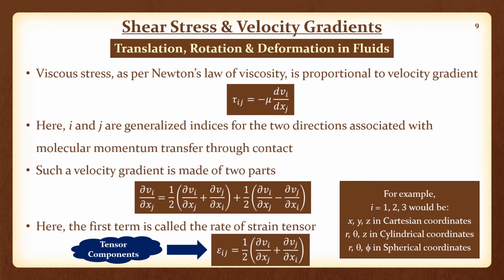Now we move on to the next part of this. So now we have defined the fluxes of molecular momentum transport, and in defining these fluxes we had to introduce the concept of second order tensor, because now we are looking at a quantity that is transported, which is momentum, which itself is a vector, and therefore we have to look at change in the direction of that momentum from one direction to another, and therefore there is a second direction which will lead to another vectorial quantity, and therefore together we got a second order tensor quantity, right?